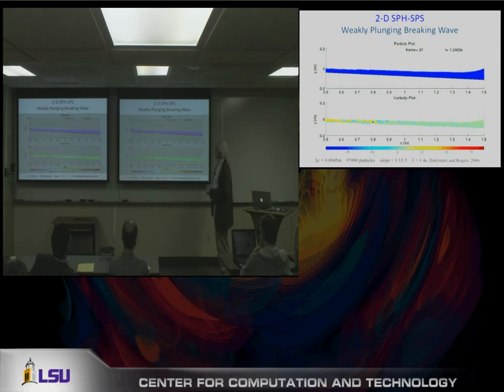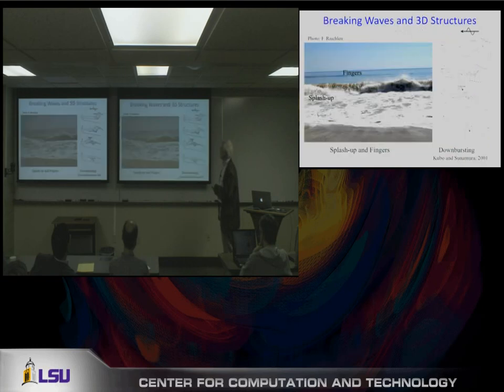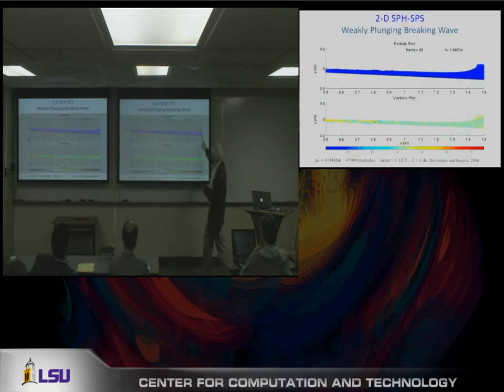And this is part of a wave tank, and you can see the wave breaking. Now it's very coarse because you can see all the particles. But the interesting thing with what you saw is that there's a plunging breaker, there's splash up, and then there's reverse breaking. So all of the phenomena that we were looking at. And then down here was the vorticity associated with a wave.